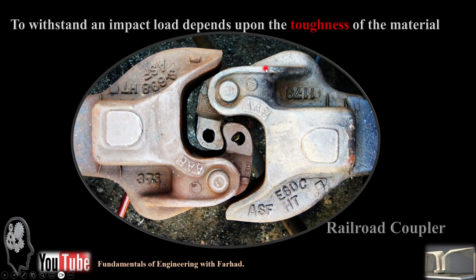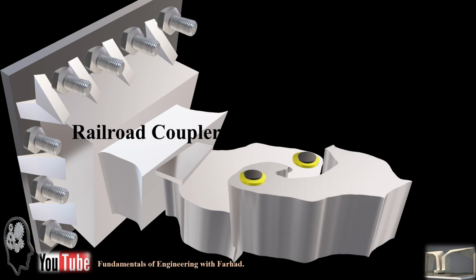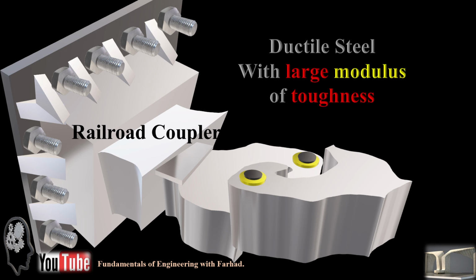We need a tough material to handle an excessive load when connecting those two wagons with each other. So again, to couple the two wagons of a train, we need a railroad coupler, which is mainly made from a ductile steel with large modulus of toughness. So it should be a very tough material to be able to handle the impact of those heavy loads.